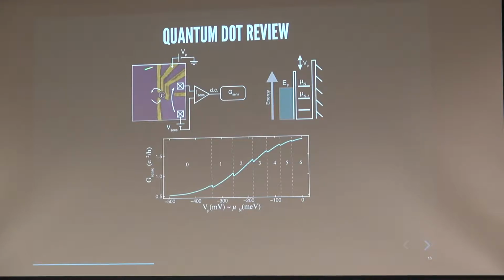So this picture you've seen already, now colorized to make the background purple. You can imagine electrons living everywhere here. Here I have nicely gold-colored metal gates on the surface. Again, the scale bar here is a few hundred nanometers across the quantum dot. And we put negative voltages on each of these gates to push the electrons away from underneath them. And so the electrons that are left are all out here in this reservoir or in this little circle, where you can see a few little arrows showing, in this case, something like a singlet state.